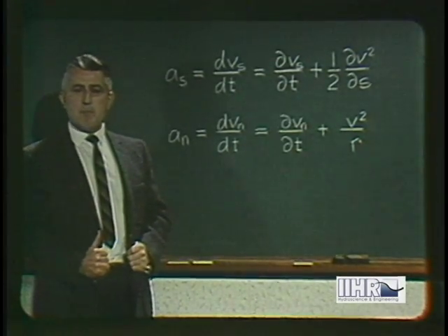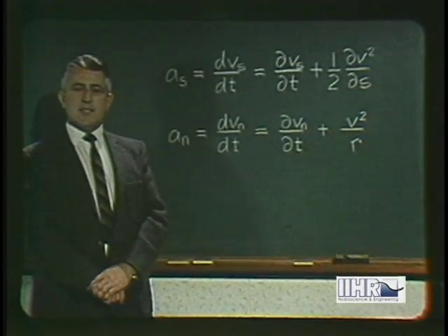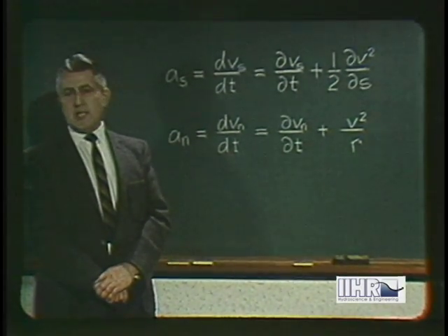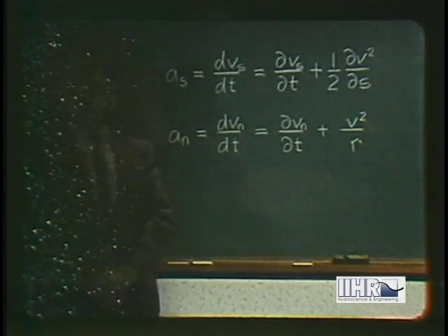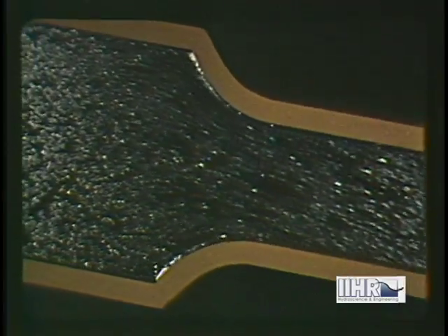Obviously, a great simplification. It is possible, however, only if the flow takes place with constant relative velocity and without change in boundary form or orientation. There are, unfortunately, many cases of flow which cannot be made steady, no matter how one looks at them. For example, a moving body need simply turn or change in speed. A nozzle need merely be varied in discharge or direction. Or a wave, instead of progressing through water at constant depth with practically constant speed and form, need only approach and break upon a beach to change its speed and form completely. Such flow can never be made to appear steady.